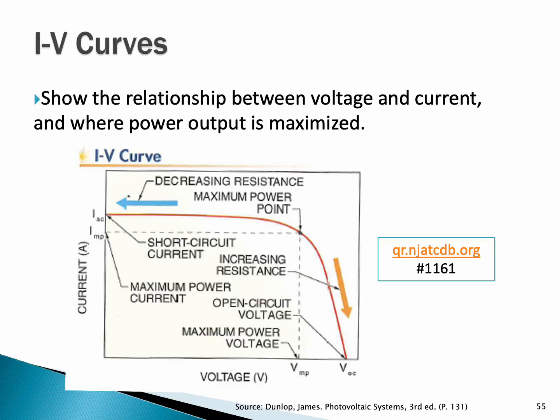We've seen this before too. I introduced the concept a few weeks ago, the IV curve. Over on the vertical axis at the very top we have ISC, or current short circuit. That's where, when I plug the leads together, I have maximum current, 0 voltage. This horizontal line is voltage. Here's the 0 mark right here in this corner. Once I engage that module or array, make it do work, then I have IMP, or current max power, and that would be at 1,000 watts per meter squared.